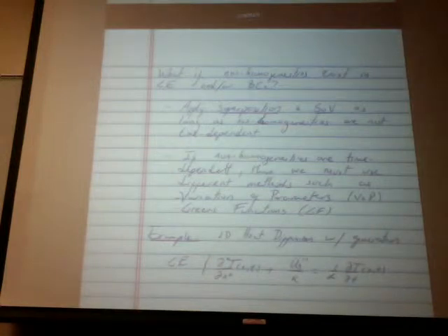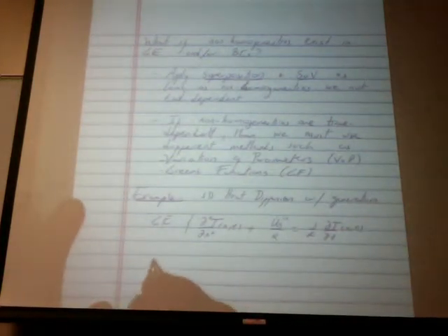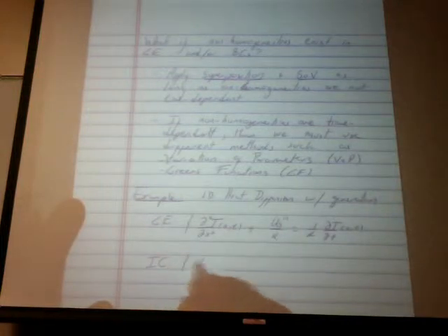Okay, so now we have a generation term, which can also be called a forcing term. It's just basically a non-homogeneity, and we're assuming that it's a constant. It's not a function of time. It cannot be a function of time. I mean, it can be a function of time, but if it is, we cannot apply superposition and separation of variables. Let's say that the initial condition is T of x and 0 equals some given function of x, f of x. Can it be a function of space? What's that? Your heat generation function. It can be a function of space, yes, but it cannot be a function of time.